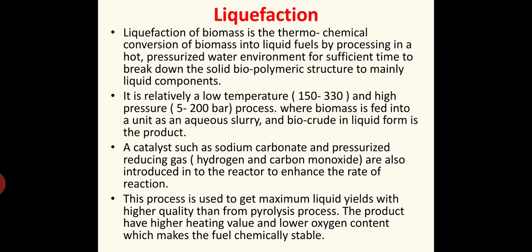So, a hot pressurized water environment and sufficient time break down the solid biopolymeric structures mainly into liquid components. By doing this process, we break that solid biopolymeric structure into liquid components. Initially it is converted into vapor form, then it is condensed to produce the liquid form. The process is carried out at relatively low temperature, 130 or 150 to 330 degrees Celsius only, but the pressure inside the chamber will be very high, that is 5 to 200 bar.